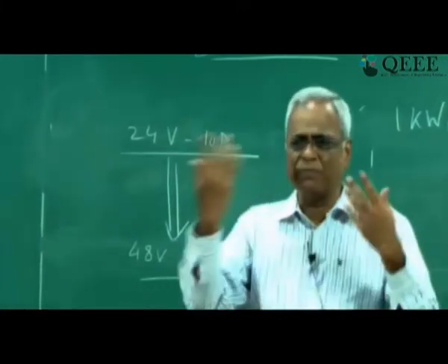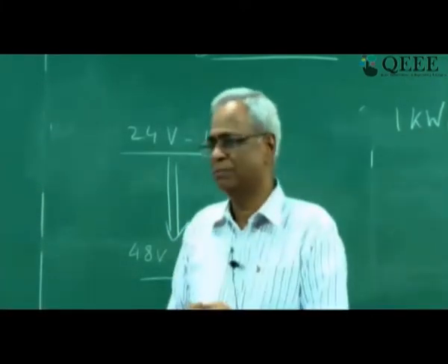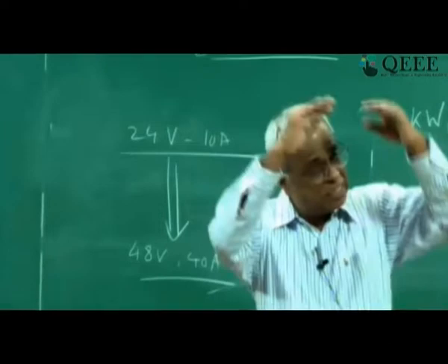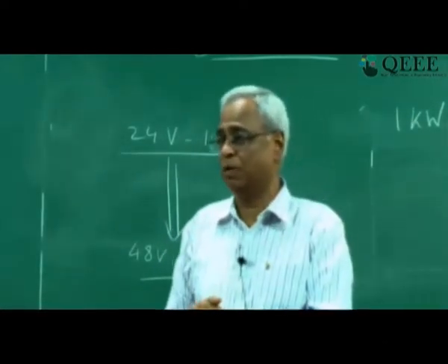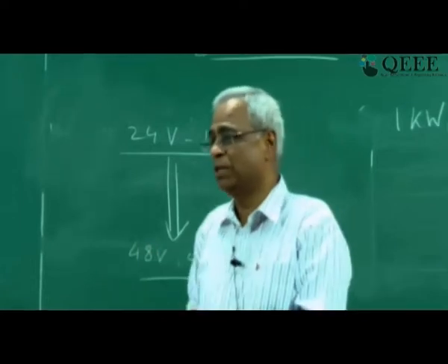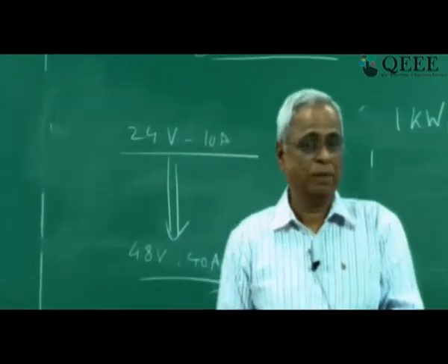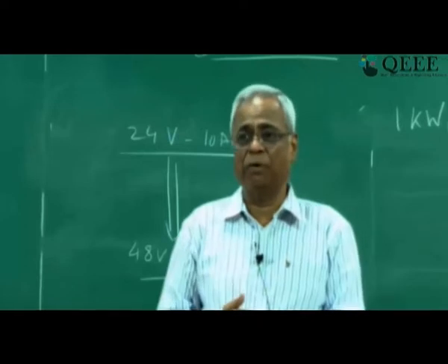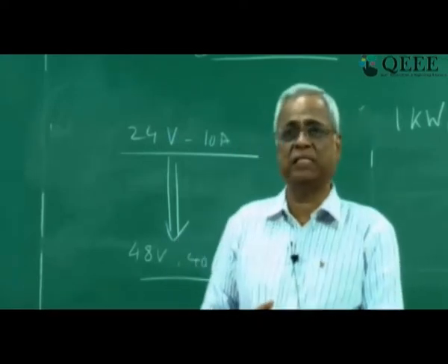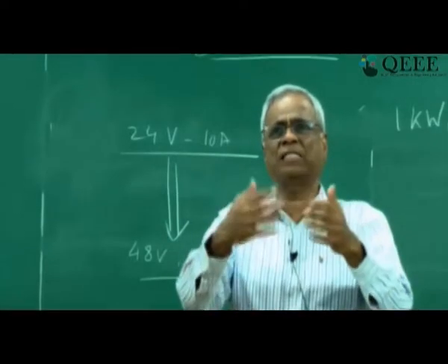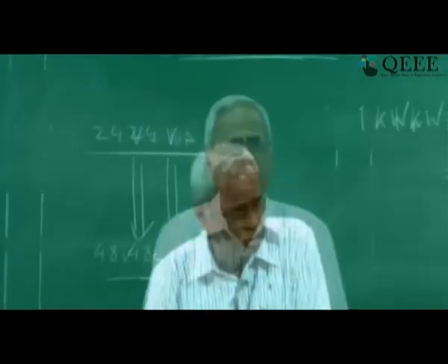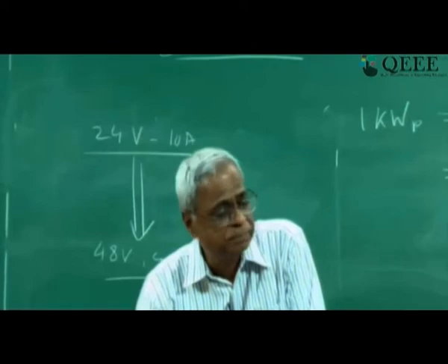If your power requirement is 5 kilowatt, for DC, remember the DC power, or even 2 kilowatt, 3 kilowatt, you may want to go for higher voltage like 380 volts. So that's a kind of thing that we'll propose and we'll talk about it in the next class. Alright. I know I partially answered, but by the end of the next class we'll be able to answer this question much better. So can we go to the next lecture please?